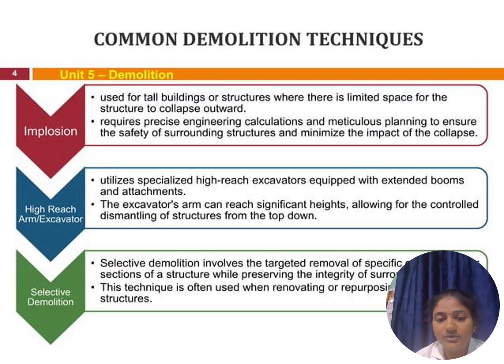And with respect to the demolition technique, the first one is implosion, which is needed for tall structures where limited space for the collapse is available, and then high reach excavators are used, which are equipped with boom materials to excavate at height. And then selective demolition, where we need to remove the surface or specific sections of the structure, is considered here.